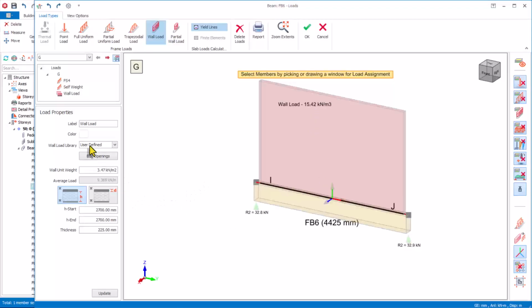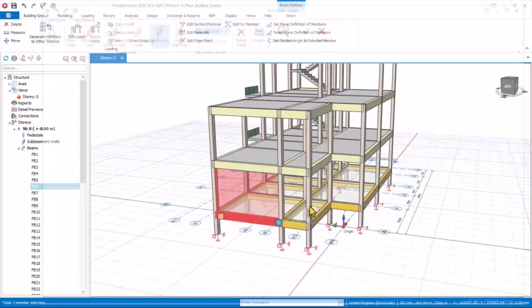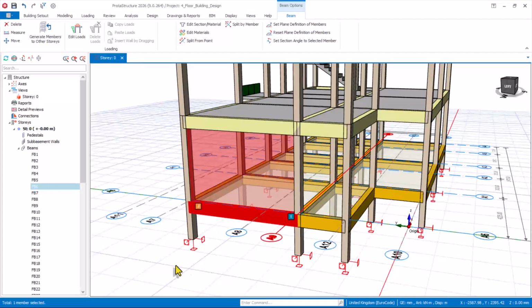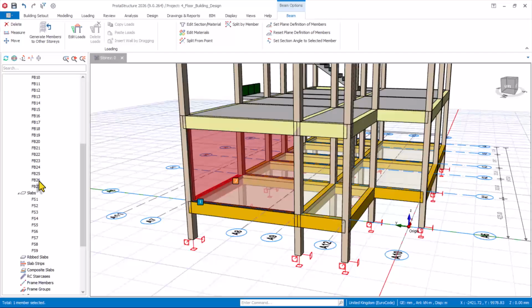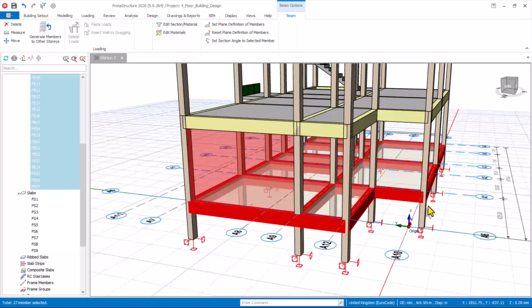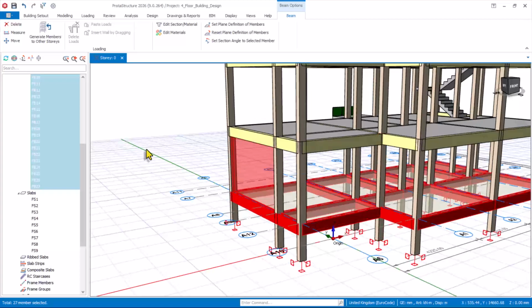All right. So from here, you can choose to use these provisions, edit opening to open. But I design just like this for the sake of unforeseen circumstances. Okay, I click on the OK option to have that applied successfully, just like this. So I have to just select the first beam right there, and then select the last beam by holding down the shift key right here to have all the beams at that level selected.